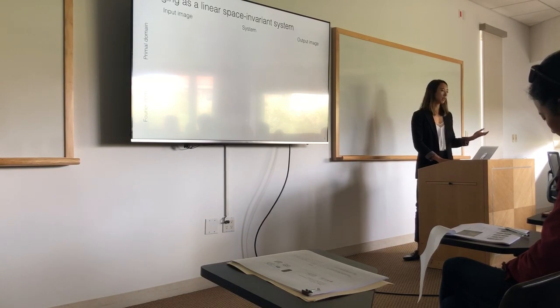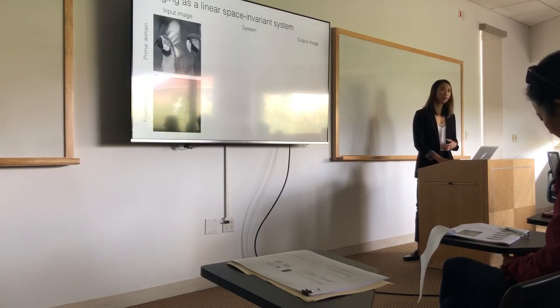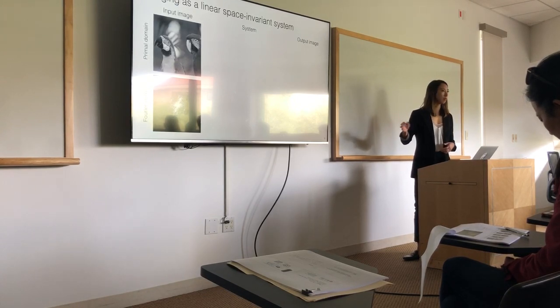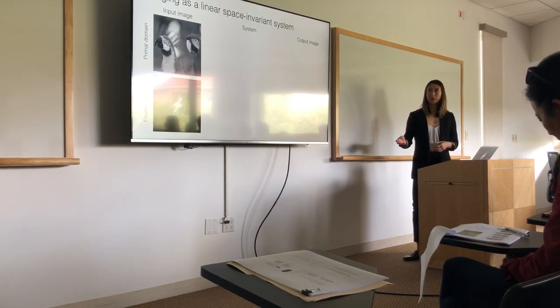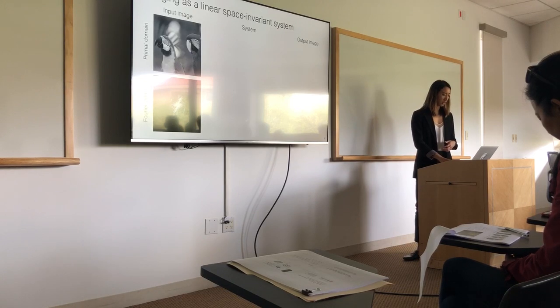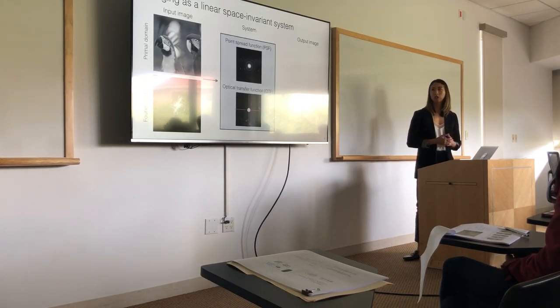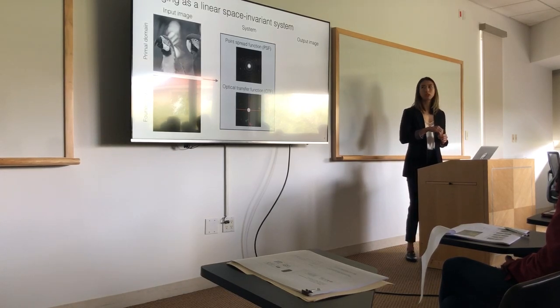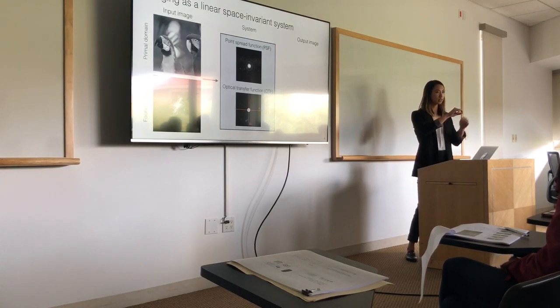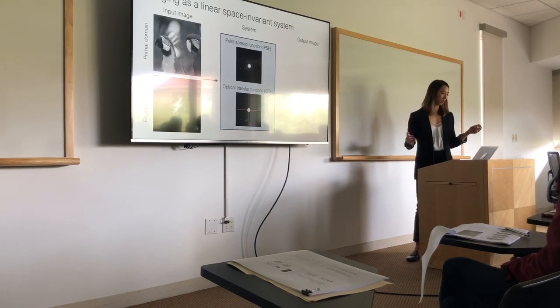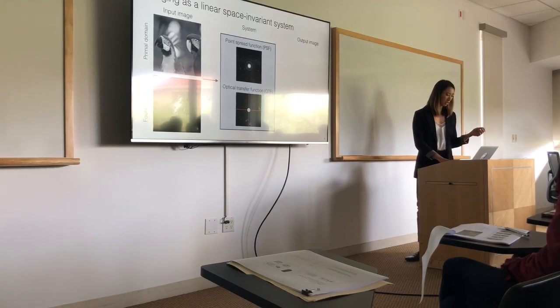So with our image processing, instead of a 1D signal, we have a 2D image, and the Fourier domain is simply the 2D Fourier transform of that image. Our system can be characterized by a point spread function, or the Fourier transform of which is an optical transfer function, and that's essentially this 2D impulse response that describes how a point in space spreads out on your camera sensor. In this example, we're looking at a low-pass filter.